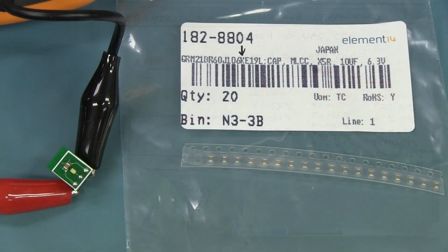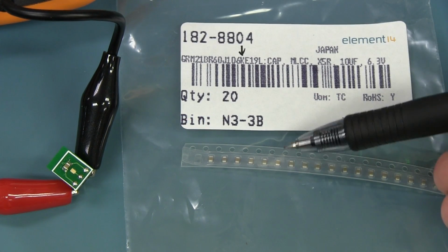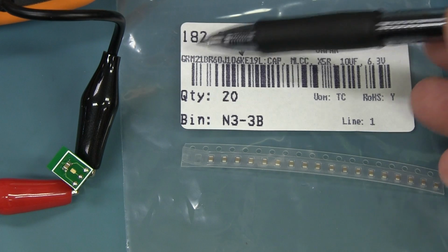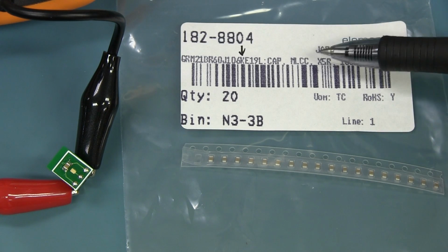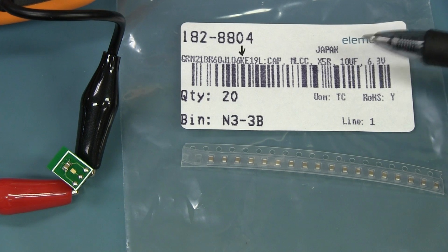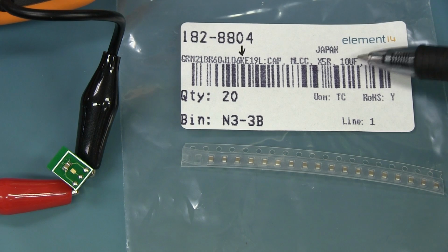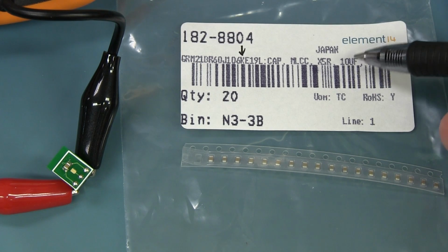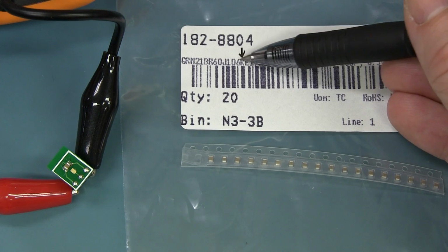Come with me. Okay, the first example we're going to look at is a typical 0805 Class 2 ceramic capacitor from Murata, one of the top manufacturers. And here's the full part number. Got this from Farnell's, and it's a multi-layer ceramic capacitor. X5R, basically the same as X7R, it's just slightly lower temperature. Nominal 10 microfarads and 6.3 volt rated. So one of these low voltage rating ones, you typically only use them on 5 volt or 3.3 volt rails or something like that.